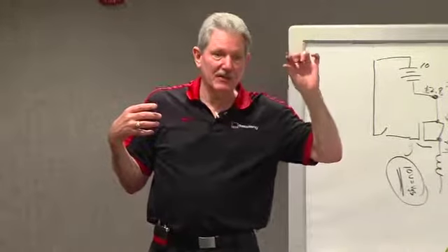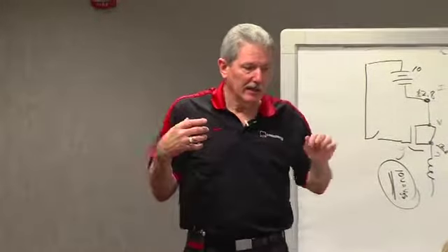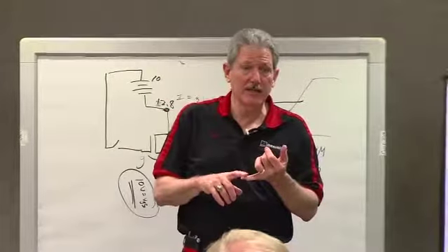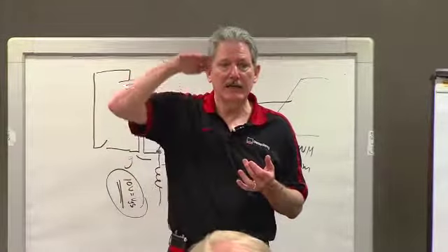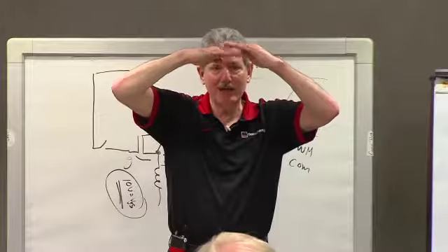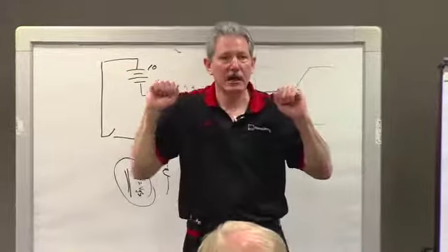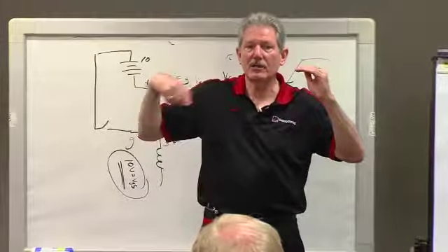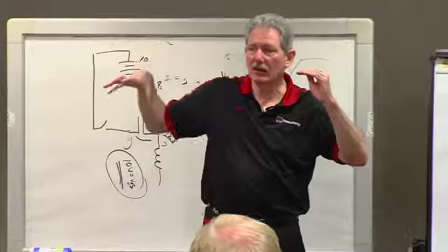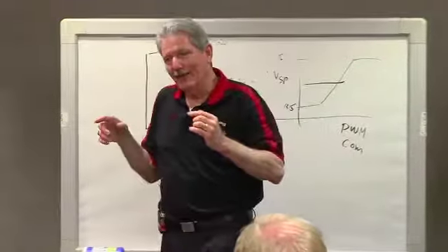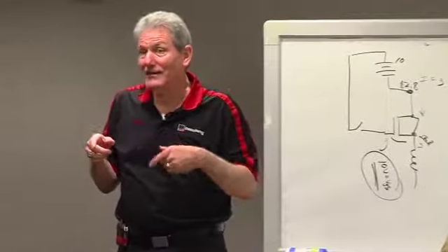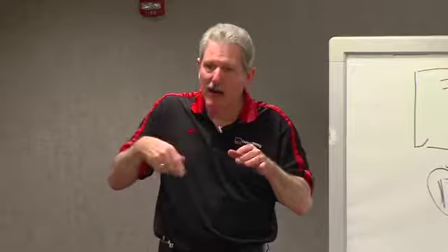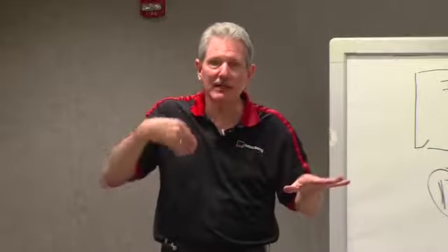So one of the features, if you want to call it a feature, that we've developed is a thermal shutdown. It's on most of the regulators today, the ASICs and the ASSPs, and that is to have a temperature threshold. When you get to that point, the regulator stops regulating or drops the voltage to where it allows it to cool off. As soon as you stop generating current, then the alternator cools off quickly. But one thing you want to make sure you don't do is indicate a fault. So with thermal shutdown, the alternator throttles back to cool it down, but doesn't give a fault indication.